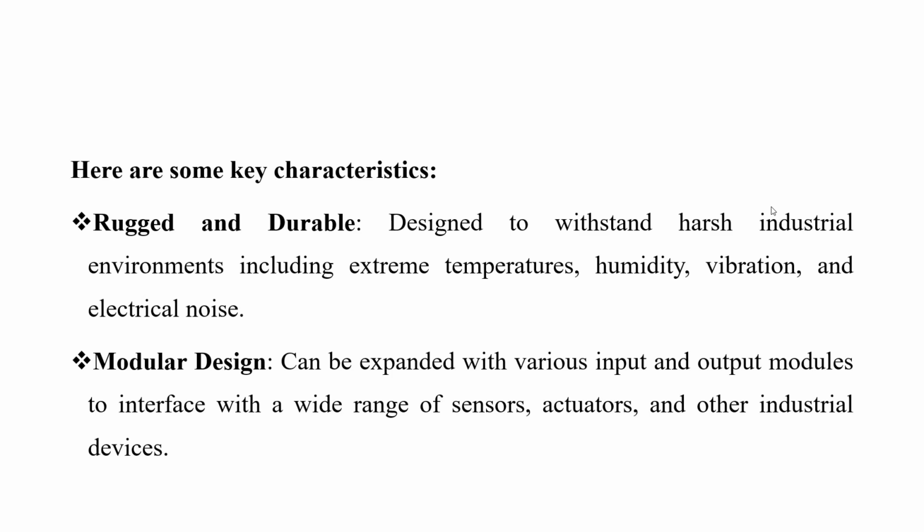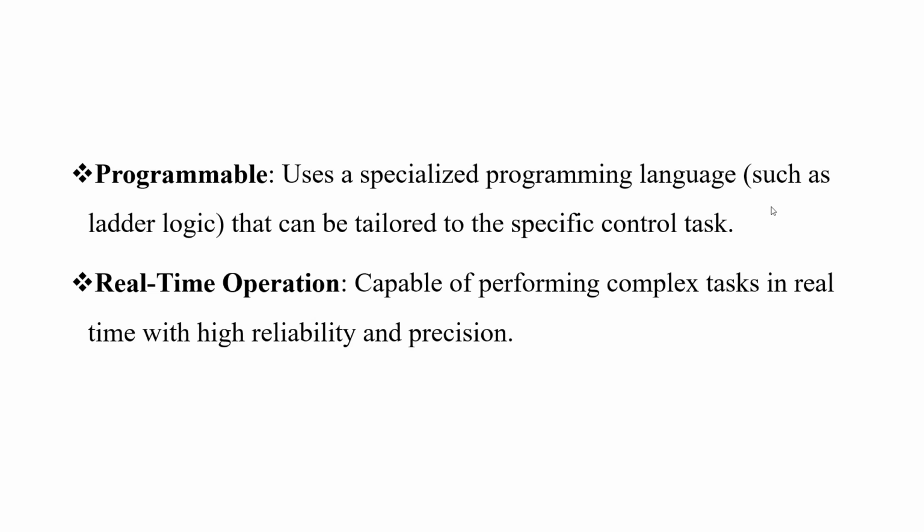An advantage is that a PLC can be designed with provision for future expansion, and therefore you can expand it with various input and output modules, and be able to introduce other functions that you want this PLC to play. It is also programmable, using specialized programming languages: ladder logic, functional block diagrams, instruction list, and structured text, all designed to perform specific control tasks.